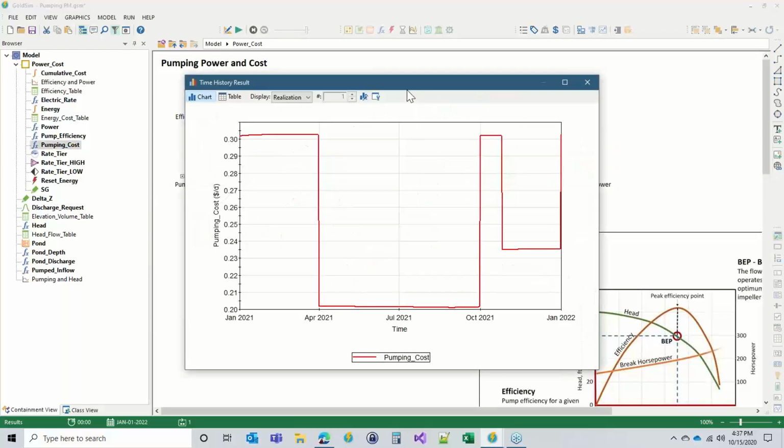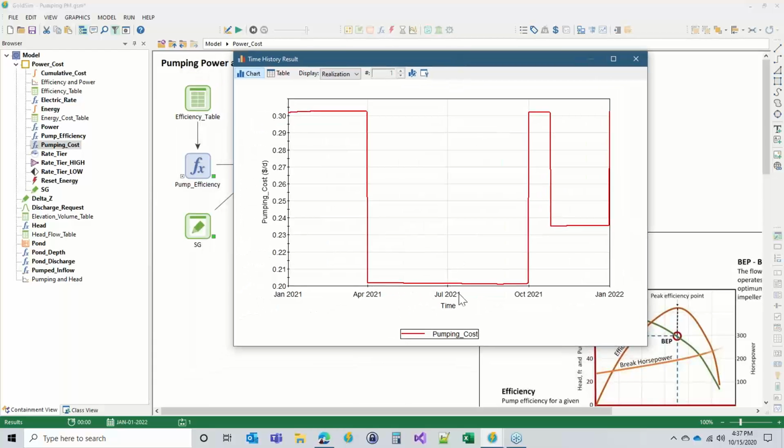And then if we look at the rate over time, you can see these are not changing much. This is a function of the water level. That's what causes these slight changes. So you can see now why, if what we're worried about is the cost, then the variable flows coming from the pump due to its pump head curve are not impacting the cost very much. So you could just assume a constant pumping and just avoid all of that part.